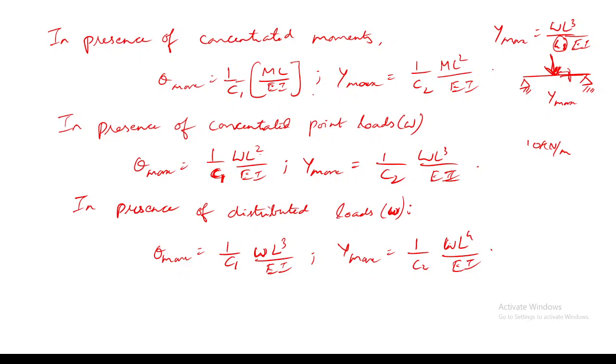So in general, when you have a standard loading where the formulas are readily available, you can see these types of variations, so it is much easier to remember the formulas. For distributed loads, you can remember it like this, only the constant value changes. For point loads, you can easily remember it like this. So I am proceeding to the problems.